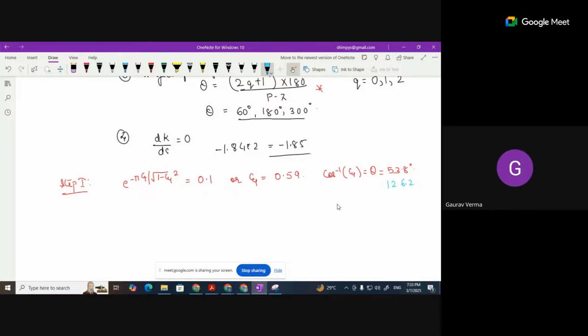Okay, that sounds fine, I'll take it on your word, but is there any justification for using the same formula for higher order systems? We have taken a second order system, but in general, we can use this formula for calculating the overshoot for any order.